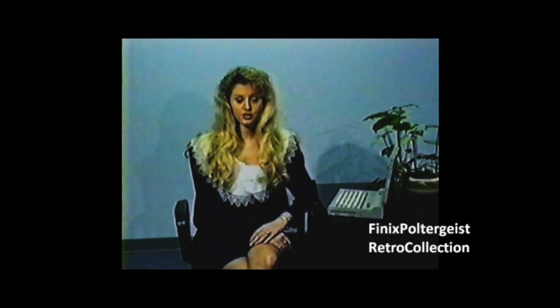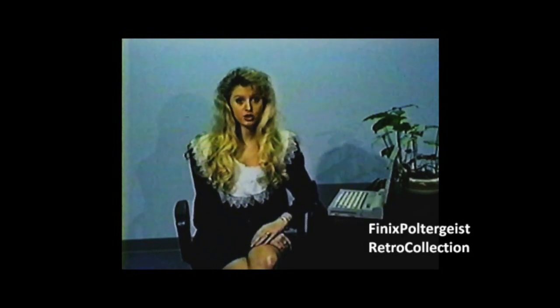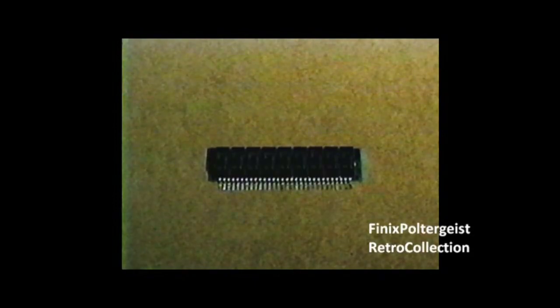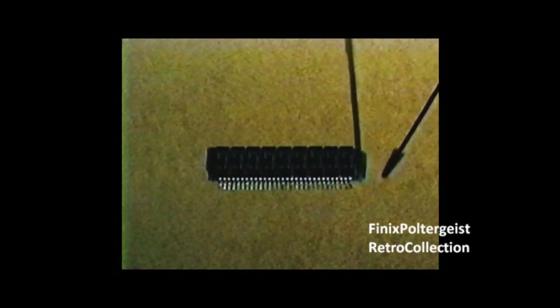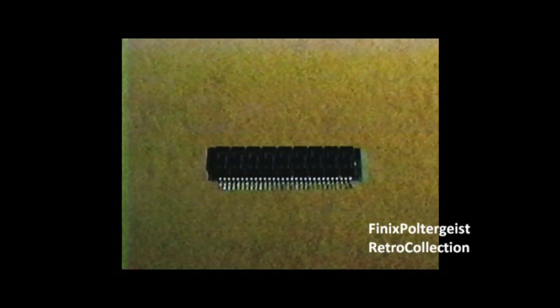Just as all computers need a CPU, they also need random access memory or RAM. There are basically 3 types of memory chips. All memory chips come in a variety of configurations. Check your user manual for your motherboard to decide what chip you need. SIPs look like this, with pins extending downward. This is a 1 meg by 9 SIP.